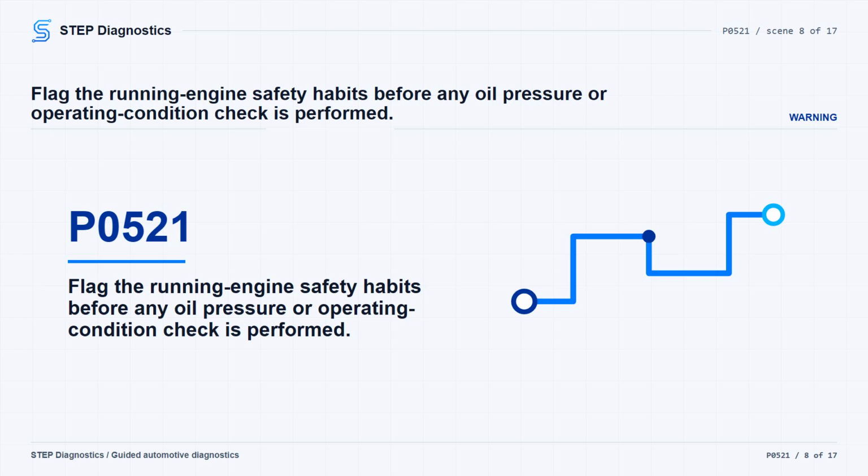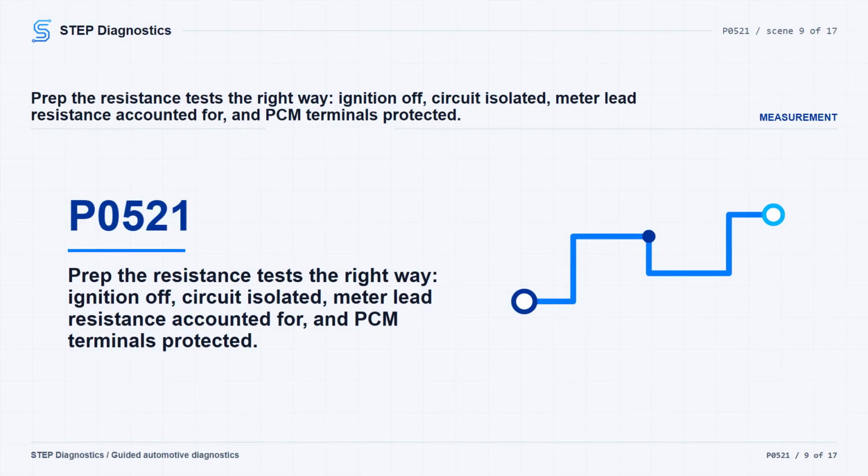When the engine is running, stay out of line with the fan, keep hands away from pulleys, belts, and the fan, and keep loose clothing clear. Next, isolate and check the EOP pressure signal circuit for high resistance. The ignition must be off when checking circuit continuity. Disconnect the ECU side and the sensor connector for the circuit being tested.